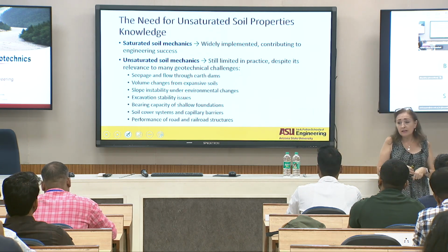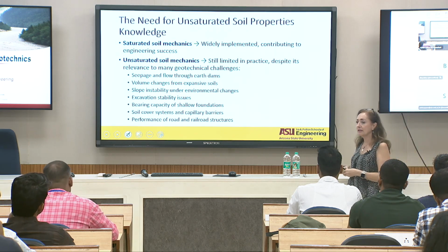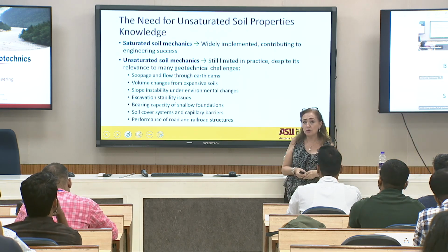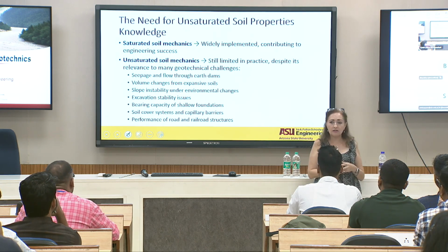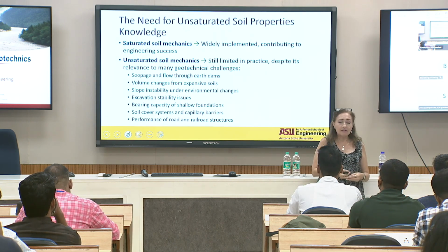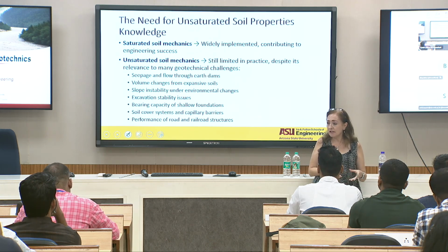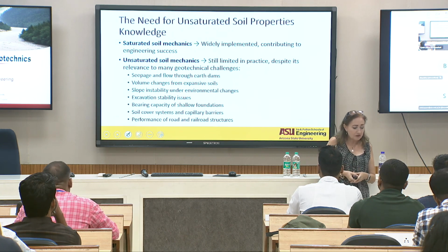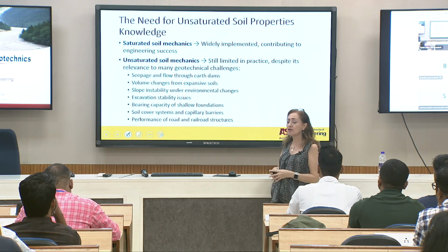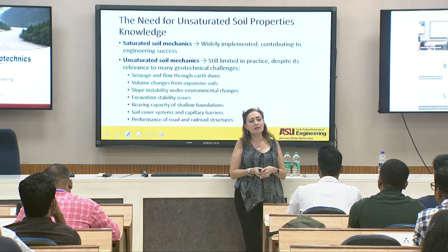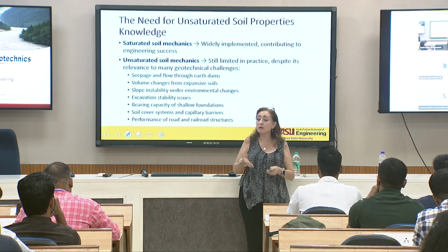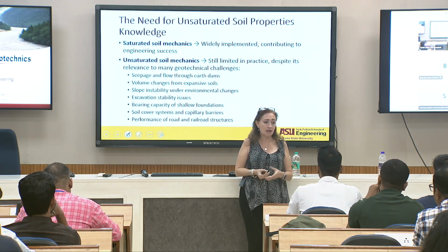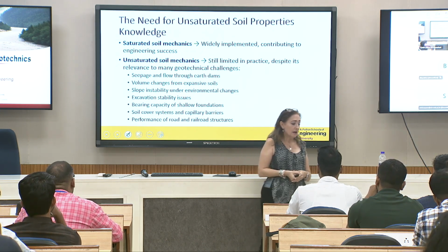Slope stability, we understand that under environmental changes we do have big problems, right? This is one of the regions where we can suffer that. Excavation stability issues are an unsaturated soil problem as well. Bearing capacity, if you have shallow foundations, usually you design a shallow foundation preferably to be above the groundwater table. It's an unsaturated condition. All right.